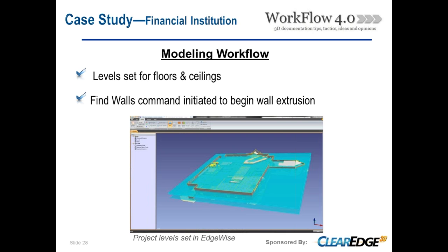Now, at this stage, it's really important to think that the end result is a Revit model. At this stage, the next thing we need to do is create the plane extraction, and what I'm showing in this illustration. So these are the levels that commensurate with the levels in Revit. We establish one on the lowest floor, and then another at the ceiling, and then you would continue that process on every floor or every level throughout the building as they exist. And again, this will ensure that the walls begin and terminate at their correct locations. So this is kind of an important step. Really simple in the software, though.